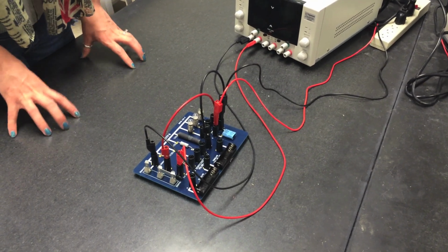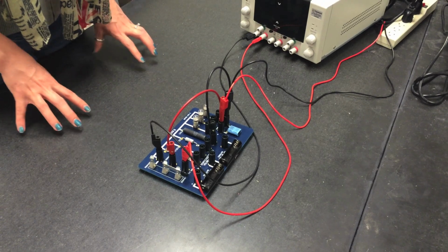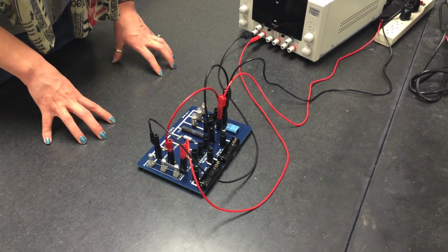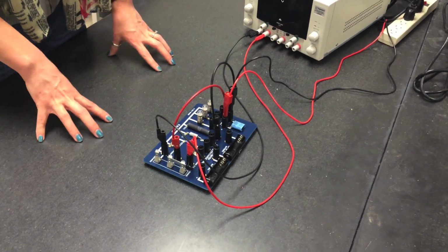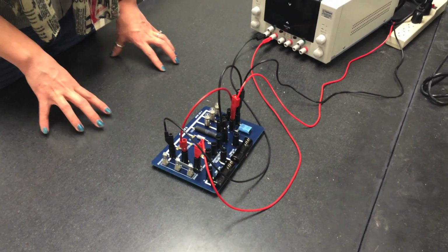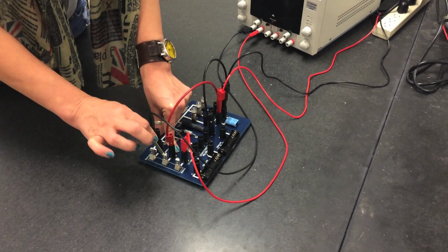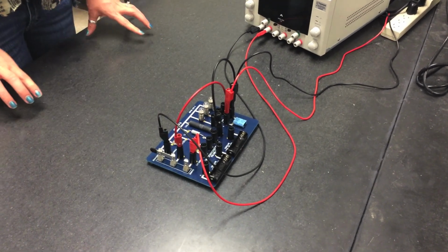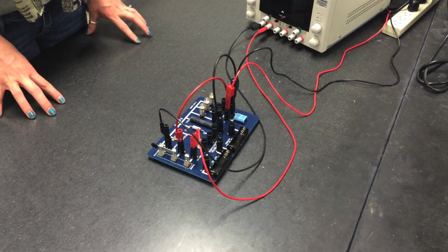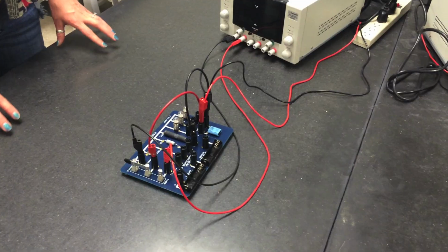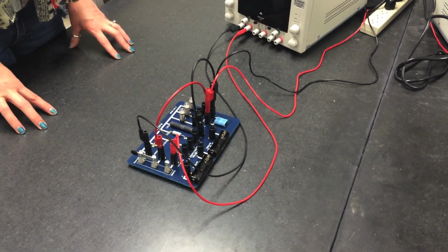Once 200 seconds is up, you're going to start collecting the data for discharging the capacitor. So now you're going to press start again and wait for a couple of seconds. The potential should now be at the maximum, around 4 volts, and after 5 to 10 seconds you're going to move this switch to discharge and wait for 200 seconds until the data collection on Data Studio stops, and then you're done collecting the data for discharging the capacitor.